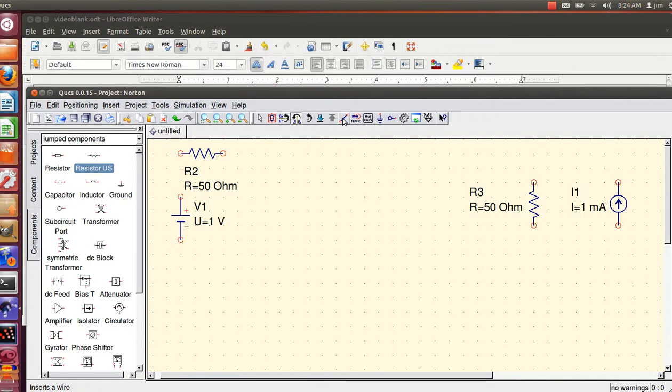So basically what we're going to do is we're going to boil down any circuit we make. If you do Thevenin, you're going to boil it down to a voltage source with a series resistance, or a current source if you use Norton with a parallel resistance. Now the values obviously will change. To make that a little more clear, this is what we would have in a Thevenin circuit. You're basically boiling everything down to a voltage source